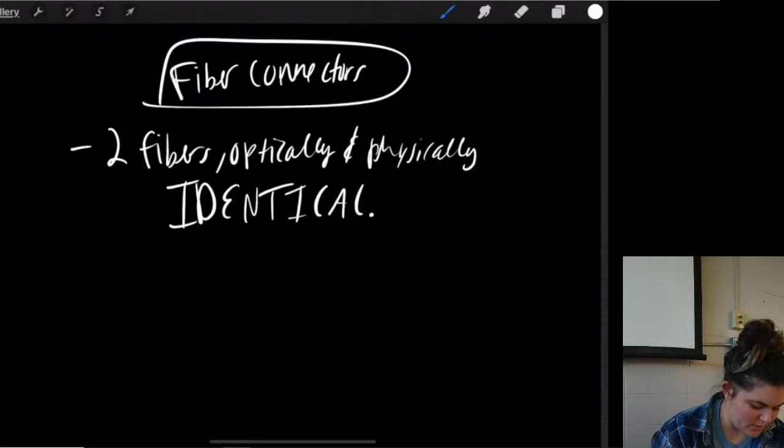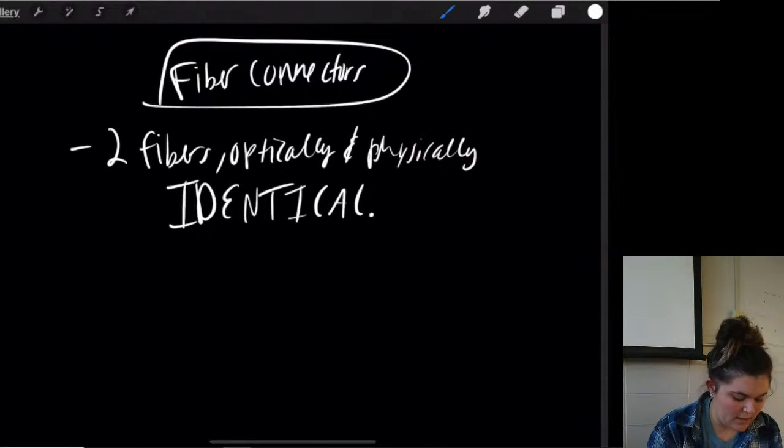Splices and fiber interconnections are often more of a negative factor than poor quality materials because of alignment problems that can arise, such as fiber gap, lateral offset, and angular misalignment. The elimination of alignment problems can be accomplished through proper installation of fiber splices, connectors, and couplers.